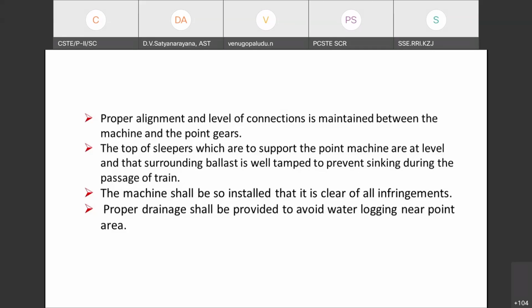Do you want to tell something regarding these notches? Sir, in universal point machine, sir, lock slide notches, close notch and short notch will be visible to everybody, sir. But detector slide notches are not visible, sir, because of the assembly and overseating of that arrangement, sir. So the detection slide notches should be the same as per notches of lock slides, sir. Then there is no need of opening and checking of the slides, sir. So different manufacturers are manufacturing as per their own, sir. In PTJ, we can see that the lock slide and detector slide notches will match, sir. In lock slide, if it is short notch, then accordingly the first notch of detector slide will be short notch only, sir. So if it is made universal, then this type of problem can be avoided, sir.